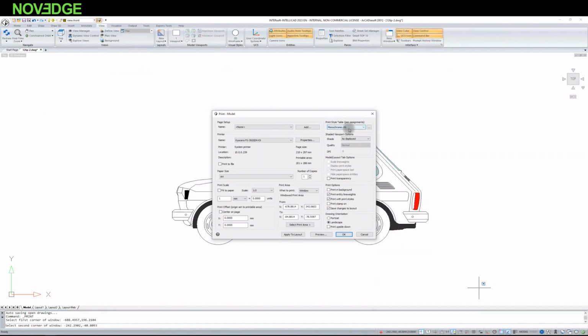Of course, you can define a template where you have, let's say, some development, and most of the drawing is actually printed in black. But there are elements to be demolished that will be red. So in the document you can draw in any color, because it's more convenient for you and it's clear, and then you turn everything but red into black.